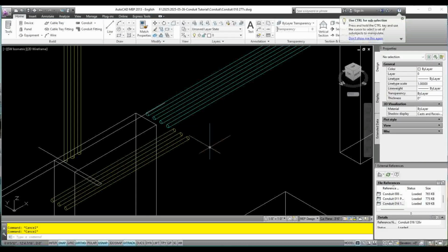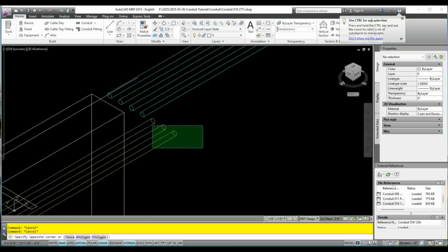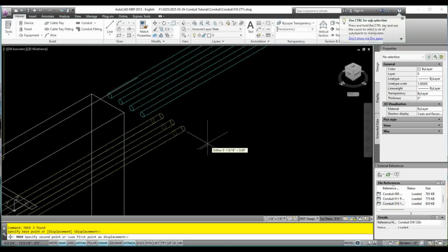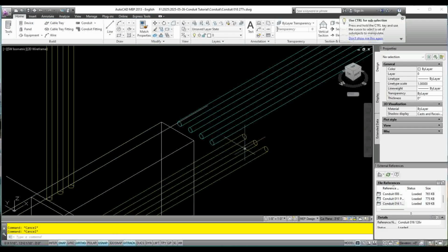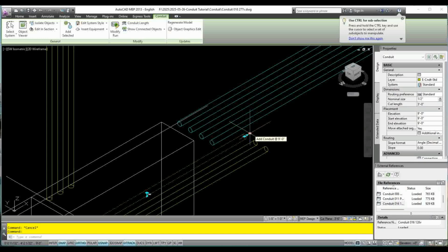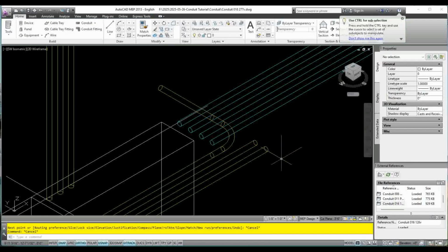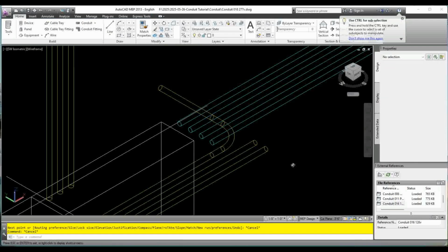You know what? Everybody, let's do this. I want to make sure it's going to run into those pipes. So click on that, highlight all 3 of those, type in move, hit enter. We're going to move it this way about, I don't know, 4 inches. Now that'll ensure that we're going to slam into these, right? So let's click this, highlight this one, turn to 90, boom. What happened? Well, let's hit our shift, center mouse button and rotate that.